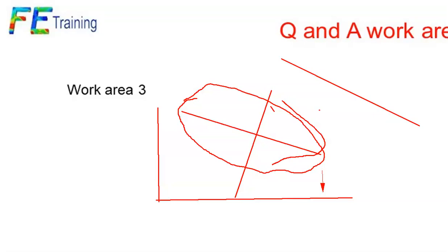In other words, there's damage. Is it tolerant of that? So these days, it's maybe quite rare to have what we call a safe life approach, where everything is designed on just the SN curve. Yes, if you're not too worried about weight, and you're happy to have a big margin, then you can apply a safety factor as you're suggesting there. But there are better ways to approach it. But if you're not sure, and maybe it's not life critical or mission critical, maybe we could take that kind of approach.